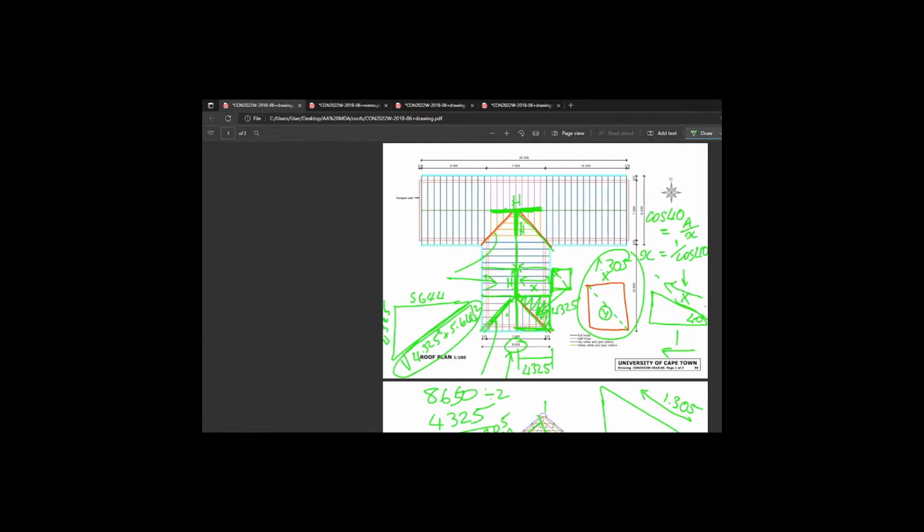It's a tricky section. That is probably the most complicated to get your head around, because you have to visualize that we're first dealing with a square on plan. Now, we use this gable end, but there's obviously no rafter here. You can't do much with the square on plan. You've got to convert it to a value that accounts for the slope. And if you were lazy, you'd not account for the slope and you'd just do Pythagoras straight. It wouldn't be correct. That might be a measure, actually, of a tie beam.